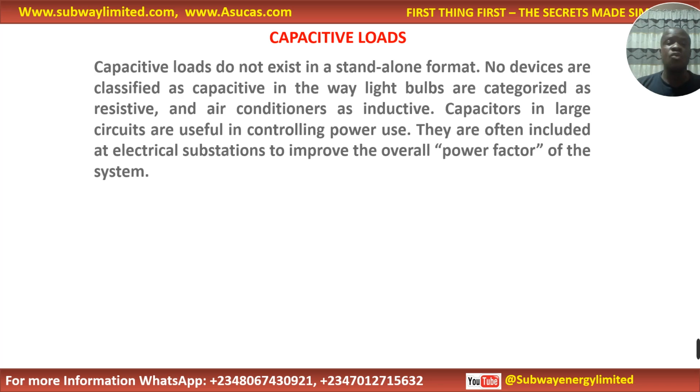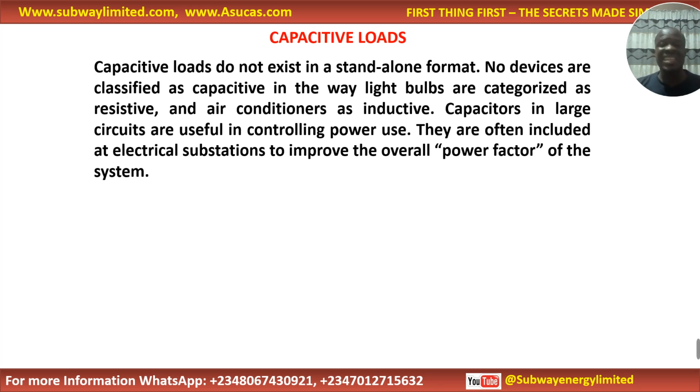So capacitive loads do not exist in a standalone format. No device is classified as capacitive in the way light bulbs are categorized as resistive and air conditioners as inductive. Capacitive loads in large circuits are useful in controlling power use. They are often included at electrical substations to improve the overall power factor of the system. Most loads we have, there is no load that is totally capacitive, making use of only capacitors.